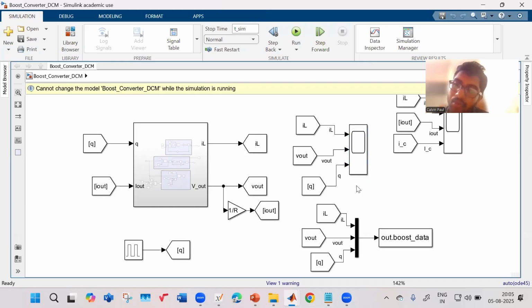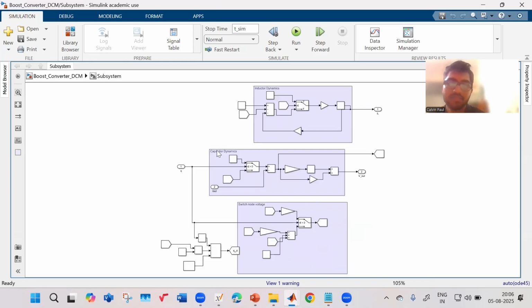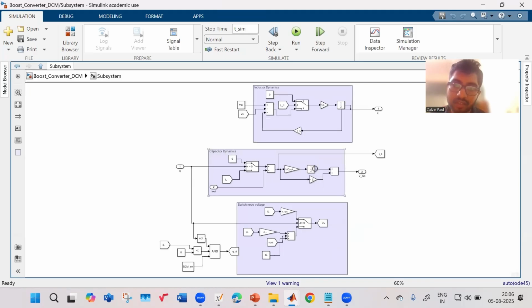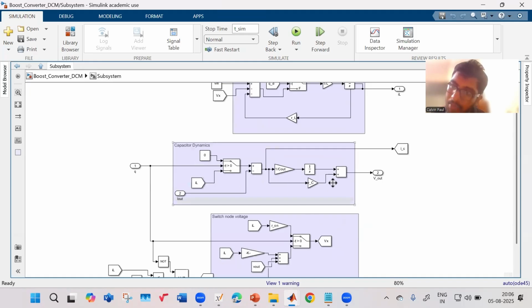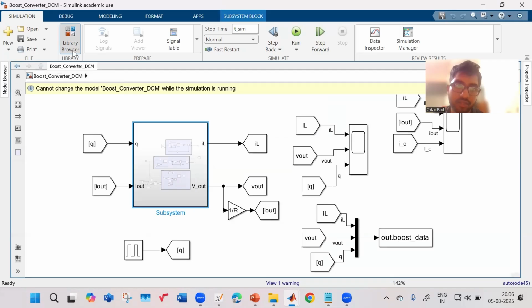This approach is more of a mathematical model based approach, where you write the equations, the linear differential equations with 1 upon s, which are switched. MATLAB is very slow. But you can also make the boost converter using the actual normal switch, like a MOSFET.